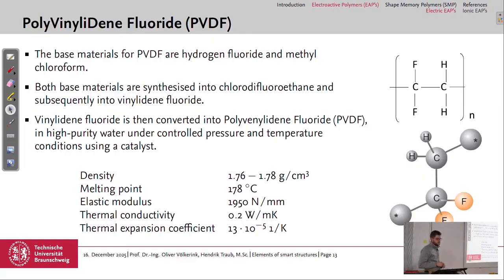So if we have the piezoelectric properties, we can use it as a functional material, we can activate it through an electric field, but to be a multifunctional material, it should also have load-bearing capabilities. And compared to other structural materials we use, like GFRP, CFRP, aluminium, the elastic modulus is really low, about 2 gigapascals. So here is a square missing, I've seen, so it's Newton per square millimeter. And therefore, I would say PVDF is more functional than a multifunctional material.